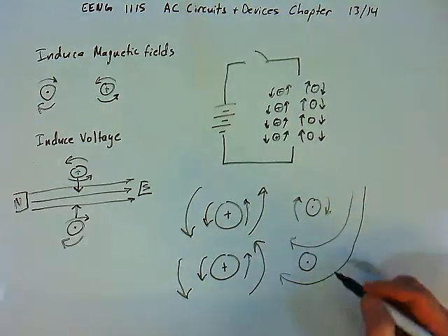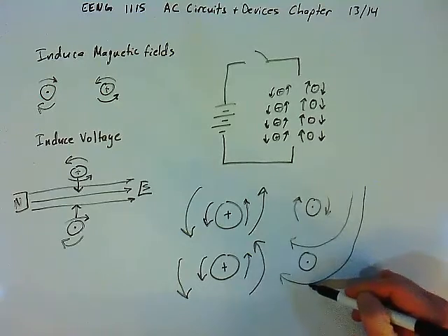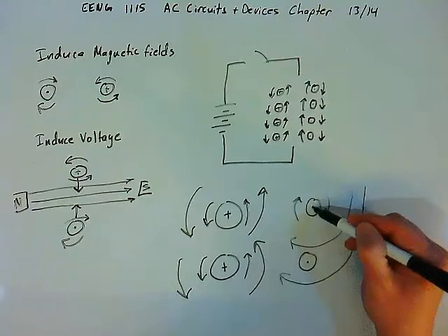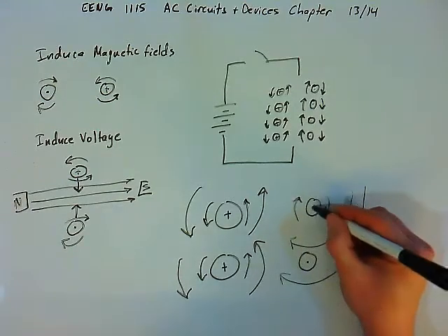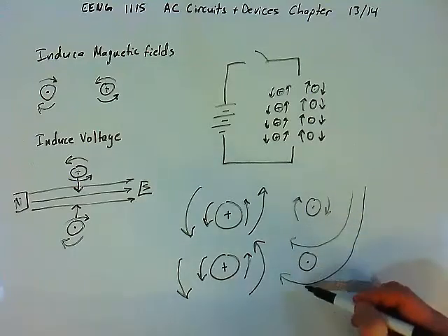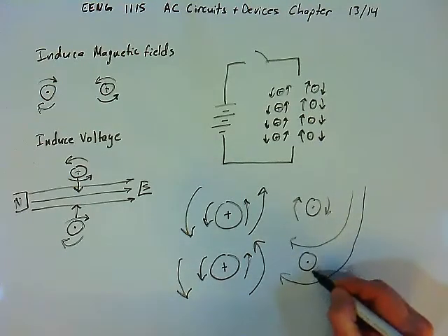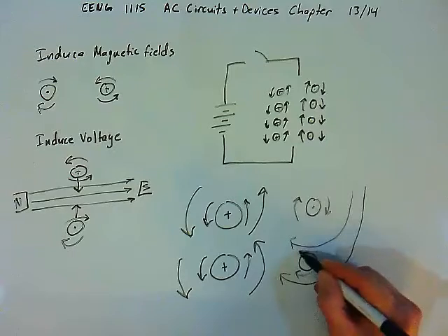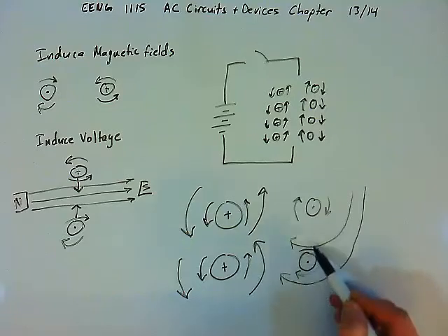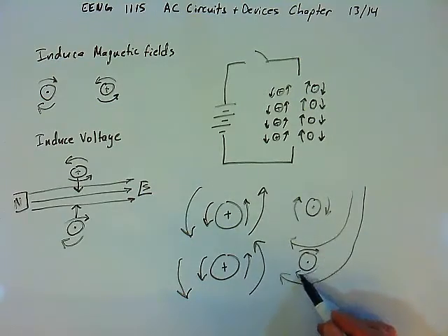And when this magnetic flux line is collapsing back toward the center of the wire that it's centered around, these flux lines are now cutting the neighbors again. And when they cut the neighbors, a voltage is induced in them that is in the same direction as the flux lines here. Right? This flux line is cutting from bottom to top. The flux line around the conductor will be in the same direction as the flux line that's cutting the wire.